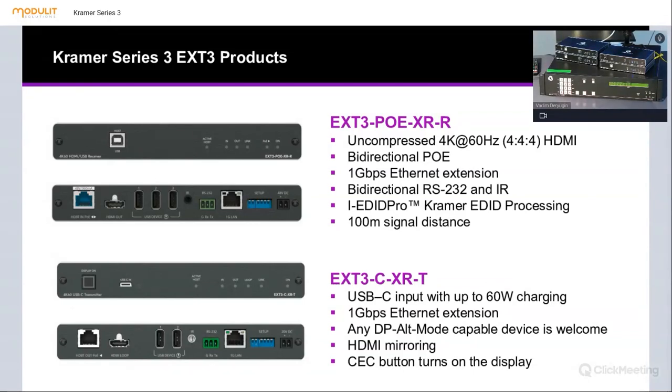But I should notice that USB Type-C doesn't mean that it has video signal inside. So USB Type-C, considering the video signal, means that the source works in DisplayPort alternative mode. So if your source supports this mode, it's okay. But if it doesn't support this mode, you cannot transfer any video data.